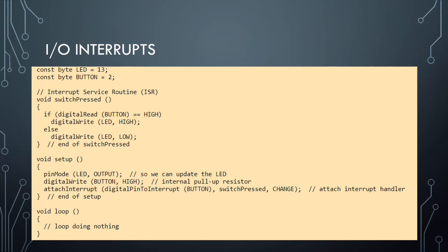So a good application of this might be an alarm, right? If you need an alarm to sound, think of like an e-stop if you're in manufacturing. No matter what's happening, no matter what's going on in the machine, you need that to immediately stop when you push that button. So an e-stop is a form of an interrupt, right?